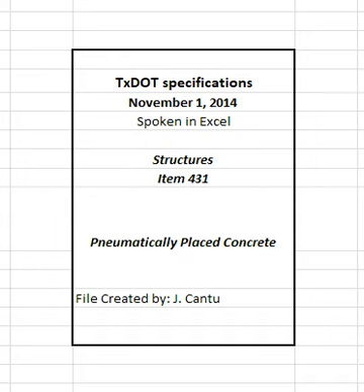Slope the concrete off to a thin edge at the end of each day's work or at similar stopping periods requiring construction joint. Thoroughly clean and wet previously placed concrete before placing an adjacent or additional section. Apply a sufficient number of coats to obtain the required thickness.